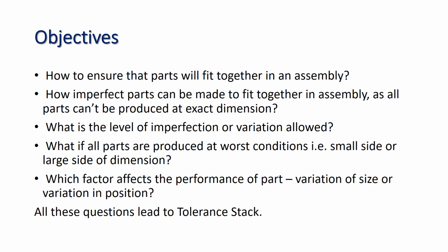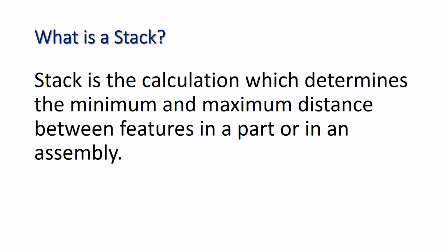And what are the factors that affect the performance of a part, whether it is variation of size or variation in position? All these questions lead to tolerance stack. What is a stack? We should determine or calculate the minimum and maximum distance between features or features of size in a part or in an assembly.